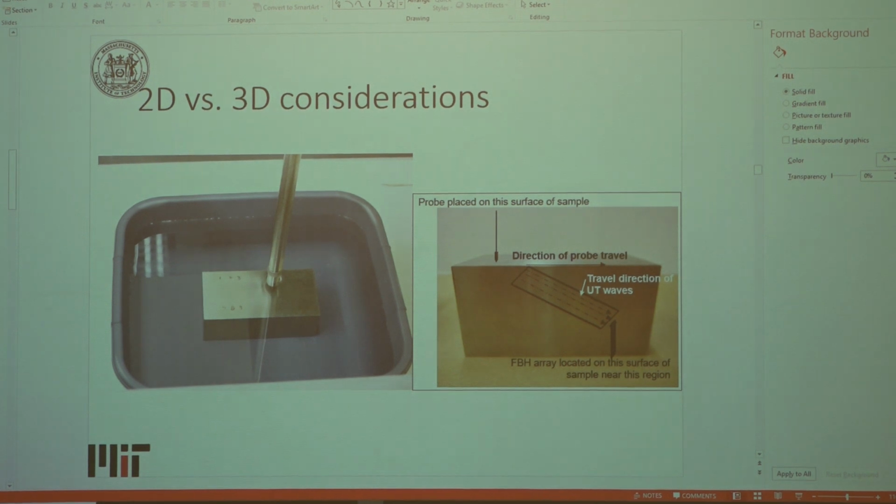For shear waves, they come in and penetrate through the sample at an angle. When you look at the image, if we're talking phased array ultrasonics, that's what's known as the sectorial scan. It is basically an arc length, a slice through the arc length. That's why, even though you can detect the flaw, you can't generally size it properly, because it will appear elliptical because of the shear wave.